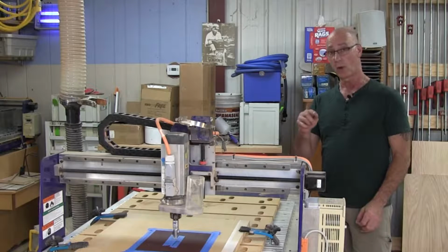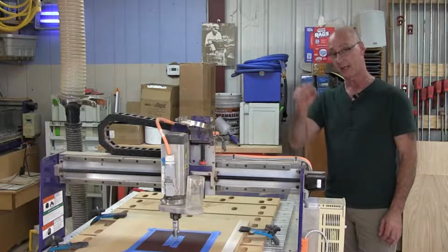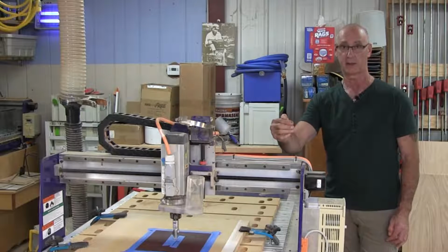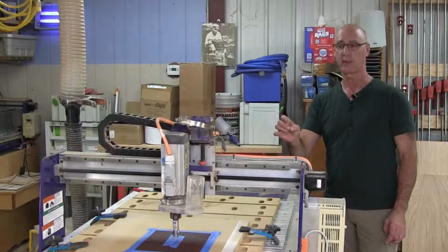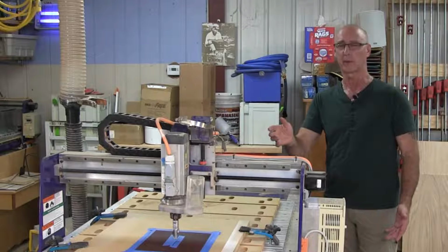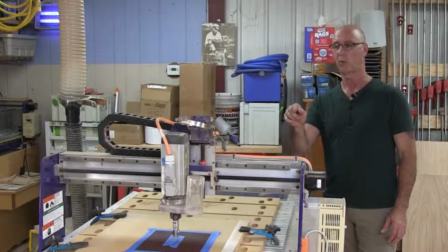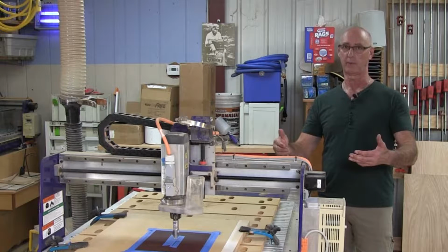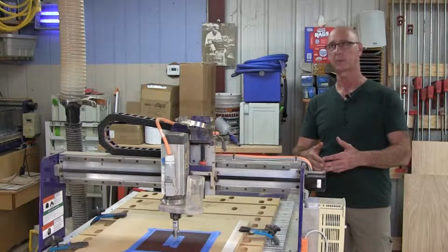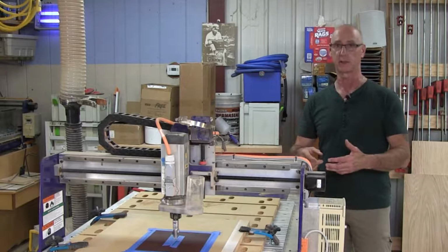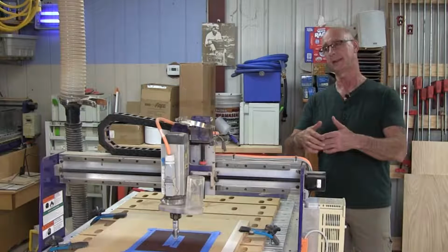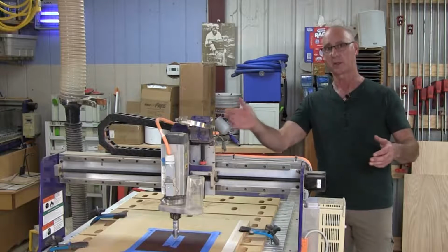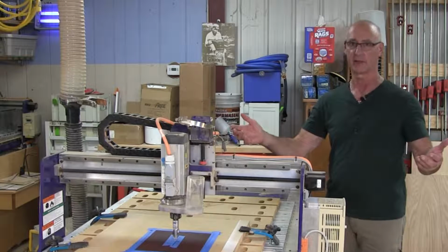So that way, by doing one axis at a time, we're getting the center of the drag knife over the center of the object. It's an extra little step you have to take with a drag knife you wouldn't have to do with a router bit, but it's a way to get centered. The other way to play this is you've got some wiggle room. If the offset is 0.16, which it is, then if the leather is 0.16 bigger than what we're cutting, you've got some room in the X and Y to make a little bit of a centering mistake.